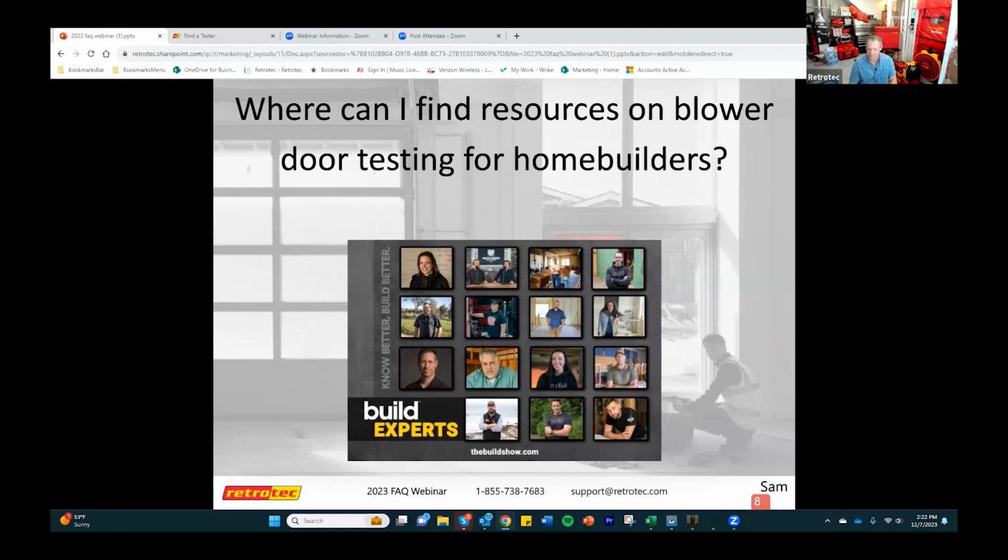And they have some contributing builders across the country that build in different climate zones that deal with all kinds of things that get into air tightness. Jake Bruton is one that I recommend following. He's out of Columbia, Missouri, and he has a method where he does a blower door test at least 3 times throughout the build. So after the air barrier is complete, before windows and doors, after windows and doors, after MEP penetrations are made, and then at final.